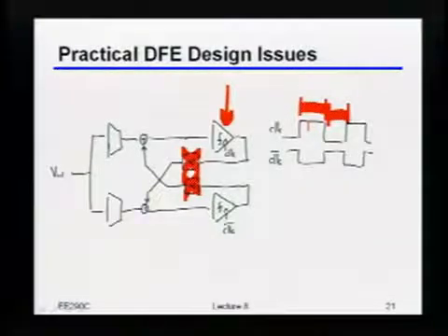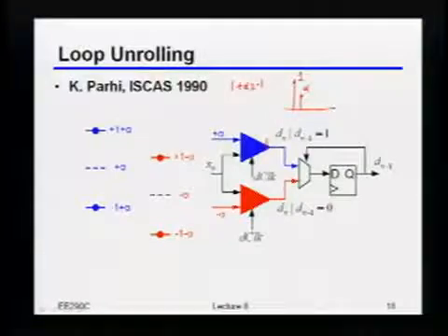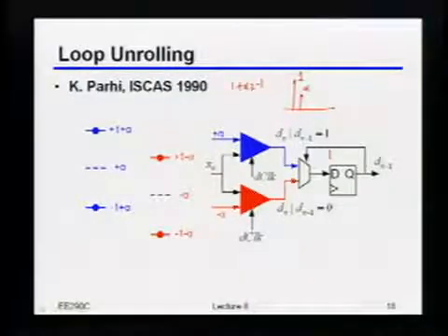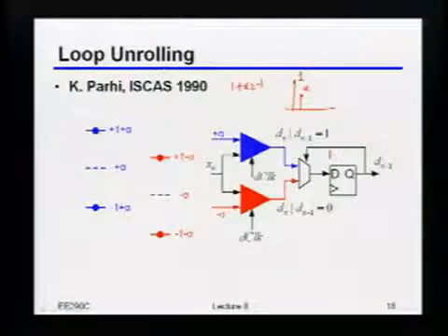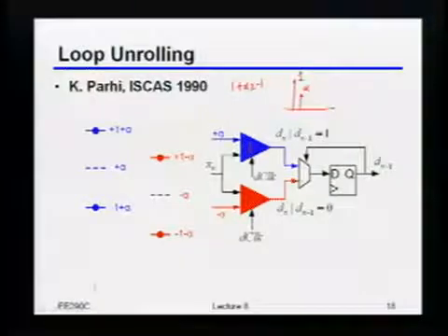Now even if you unroll it, you still have to be a little bit careful, because even in the unrolled design, you still have to make it through this path, and there's this feedback path here. This feedback path would basically be crossing from, let's say, the positive side to the negative side, because that's still how it would look. But that may actually be more relaxed than what you'd have to do to physically close it. So it depends on which one of those ends up being the critical path.